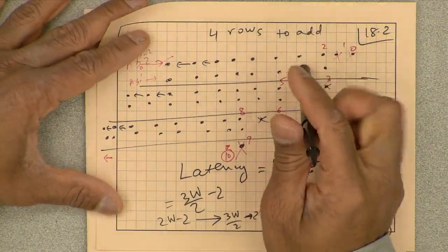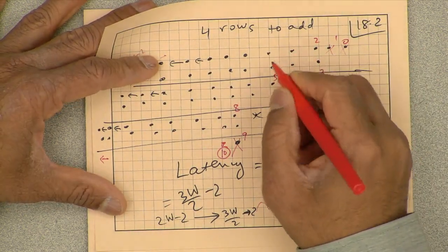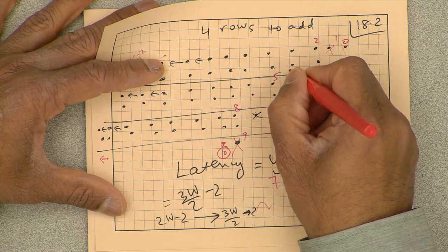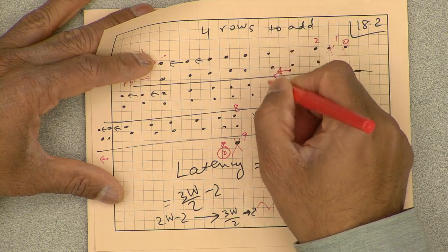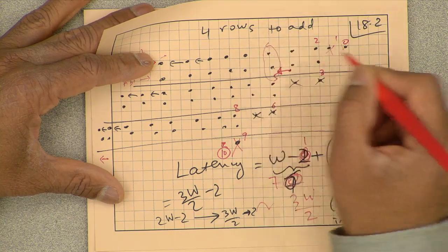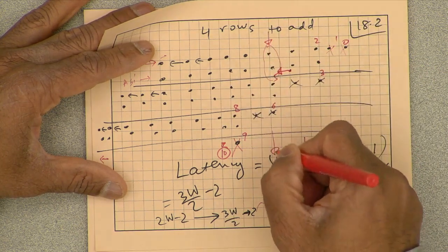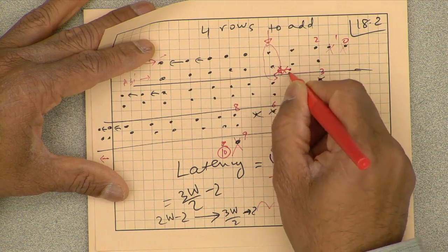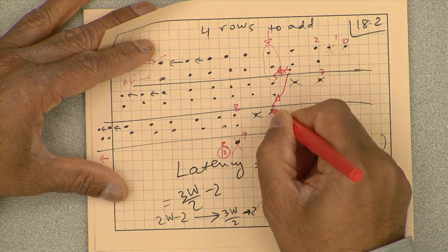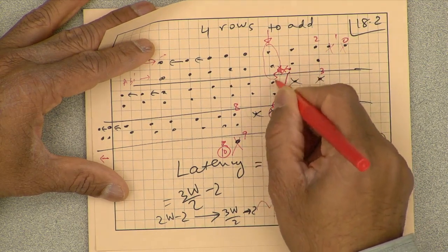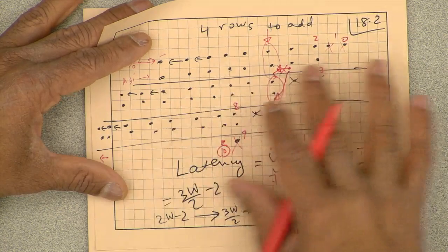still adding these in this manner, either in carry ripple or you could save the carry. So instead of rippling the carry, the carry is generated here, and in carry ripple you move that to the left, and that becomes part of this add. What is carry save doing? Carry save says, well, it's still part of that result, but don't ripple to the left, save it and put it here. It's still part of that final result, but save it and add it to the next row. So it doesn't matter whether we add, ripple or save, we still have these many things to add.